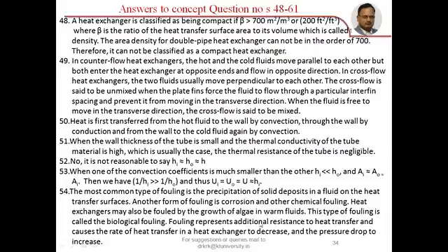But anyhow, in the normal case, we will calculate and identify. We don't go for these types of approximations. This happens in case of HI far less than H0, for example, condensation and boiling. Outside the tube, condensation occurs and H0 is very high. So the overall heat transfer coefficient becomes HI itself.